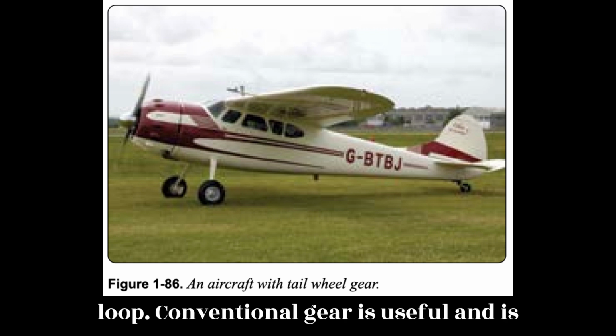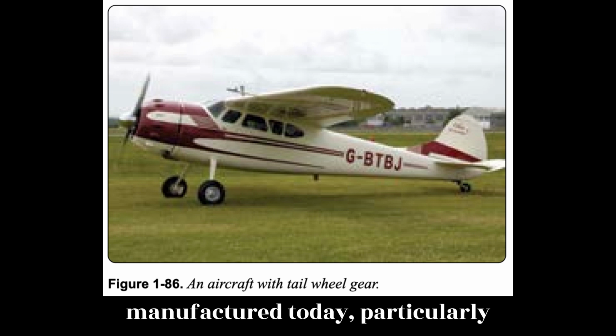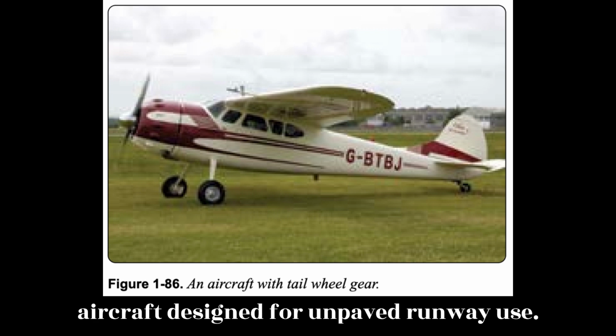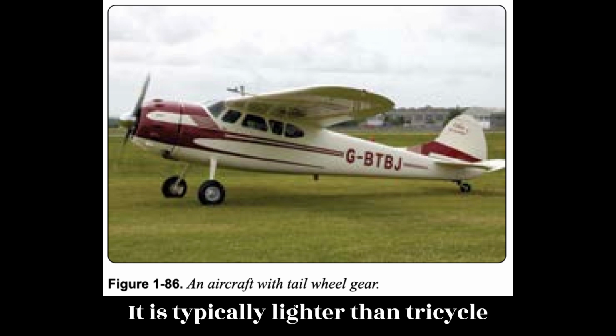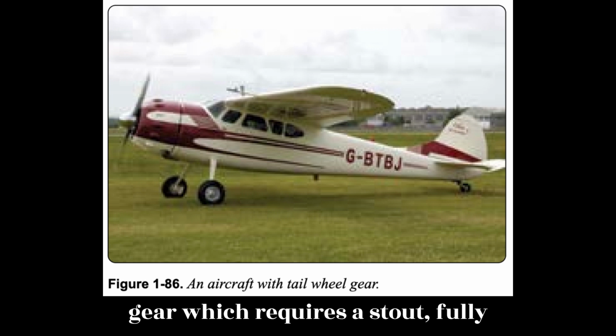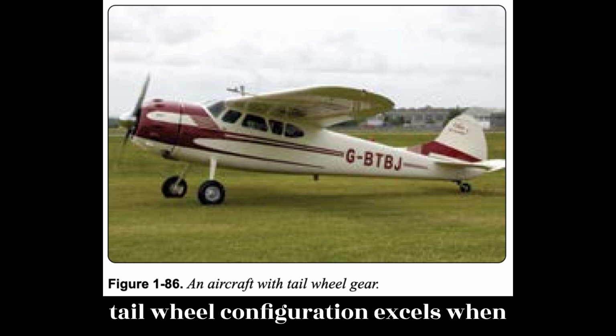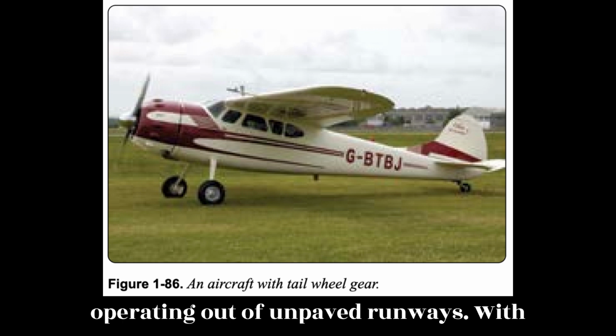Conventional gear is useful and is still found on certain models of aircraft manufactured today, particularly aerobatic aircraft, crop dusters, and aircraft designed for unpaved runway use. It is typically lighter than tricycle gear, which requires a stout, fully shock-absorbing nose wheel assembly. The tail wheel configuration excels when operating out of unpaved runways.